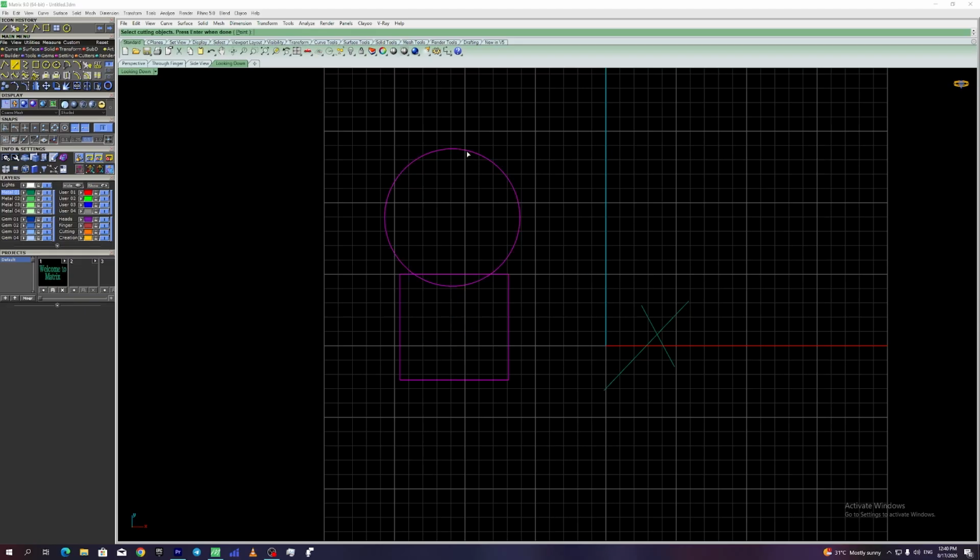Next, we select the circle as the cutting object, and then we press enter or simply right click, which, as I've mentioned before, is much faster and more natural. And just like that, the square is now divided into separate pieces at the point where the circle crosses it. You can also do the reverse, split the circle using the square. Once you've split both objects, you can join the pieces together in new ways, giving you endless creative possibilities.